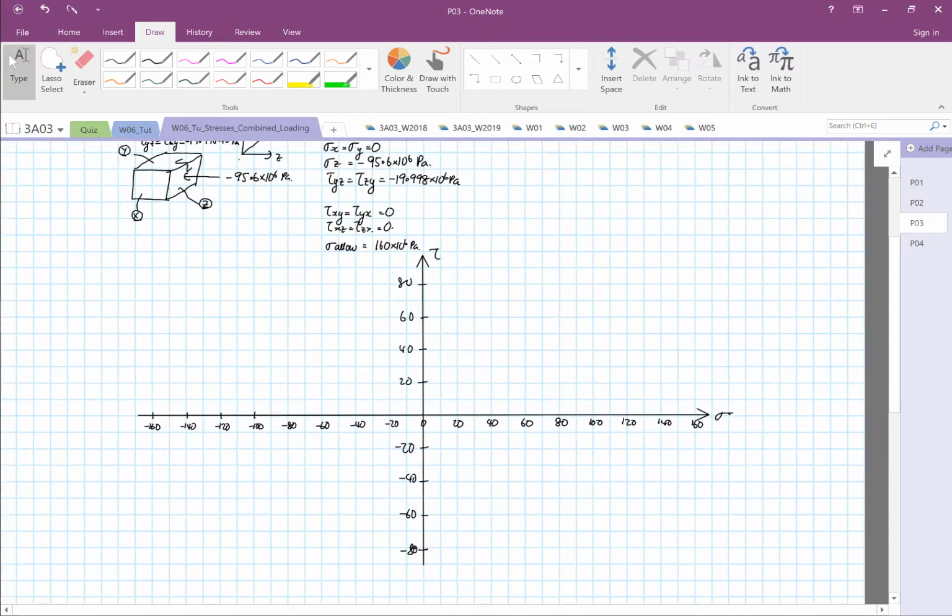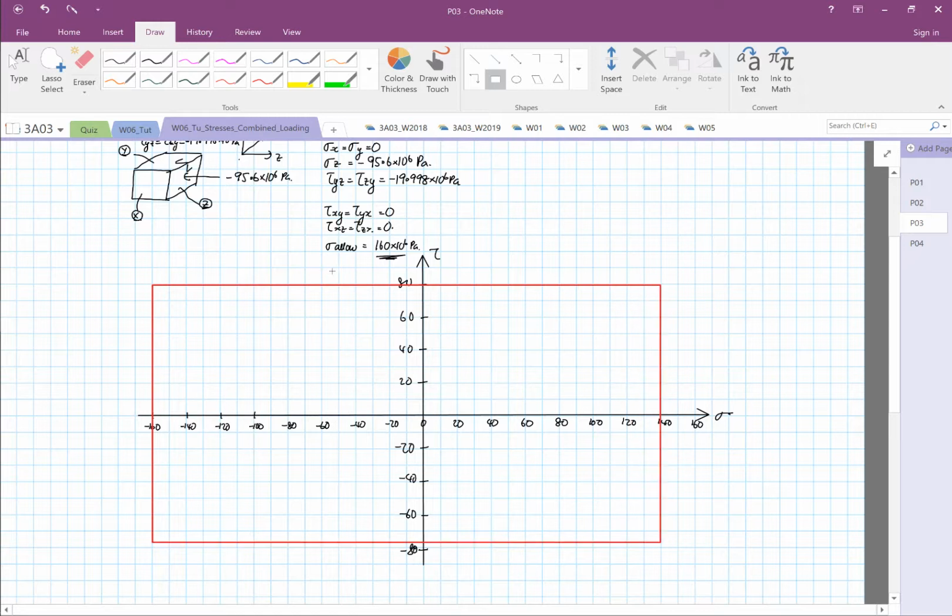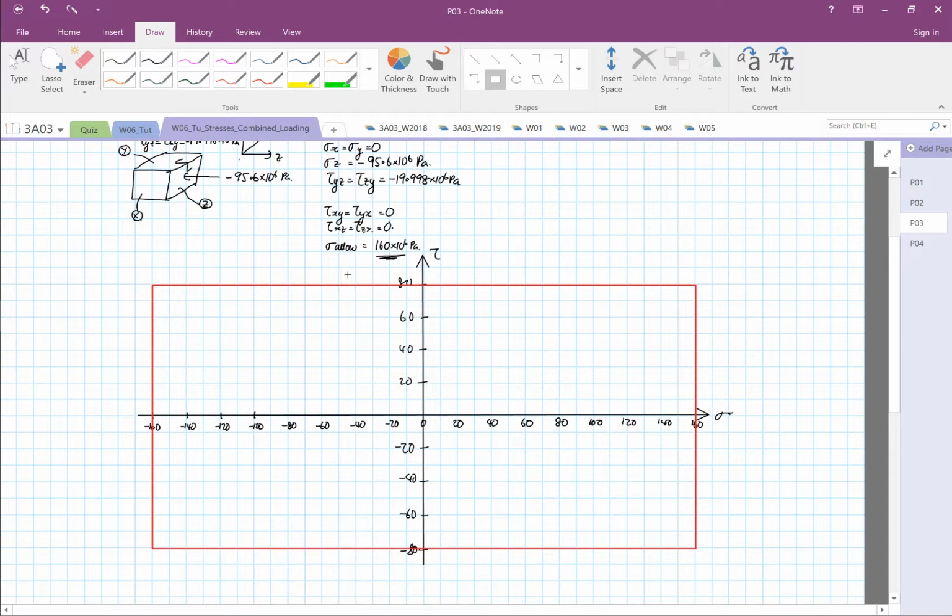Right. So what I'd like to elaborate is the allowable stress. For our diagram over here, we realize that anything outside this red box, the material will fail. I know I've not taught this yet, but I want you to get this information. So anything that's out here, the material will fail. Anything above 80 megapascal, why 80 is because of Tresca. Later on, I'll describe what Tresca is in another chapter. So the shaded regions are the no-go zone.